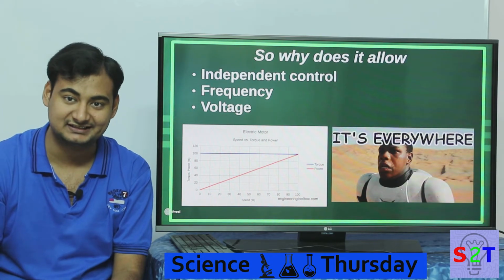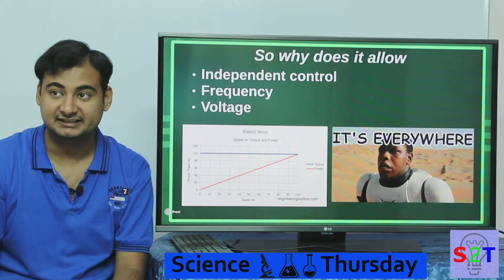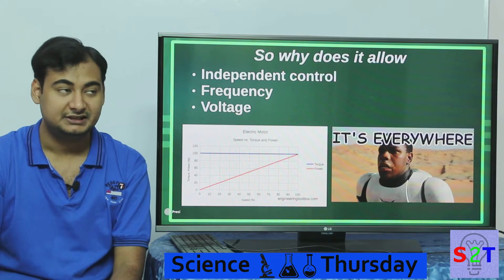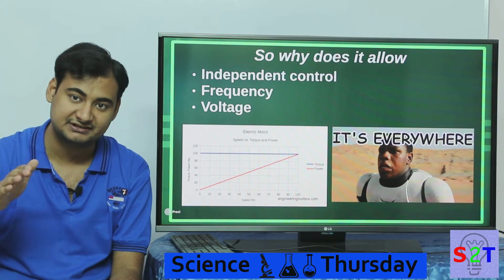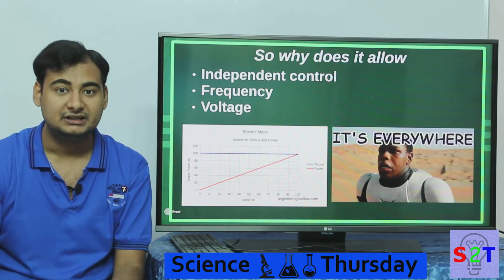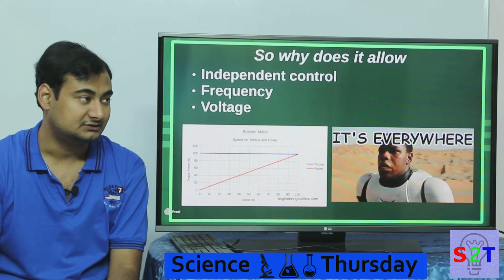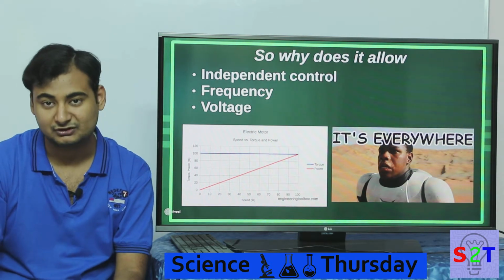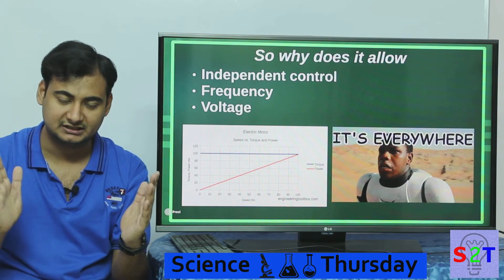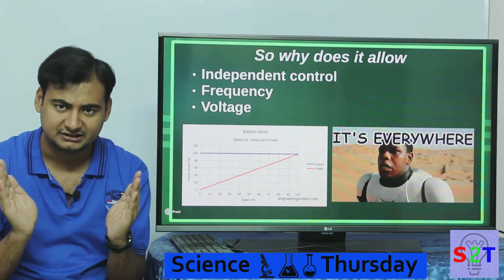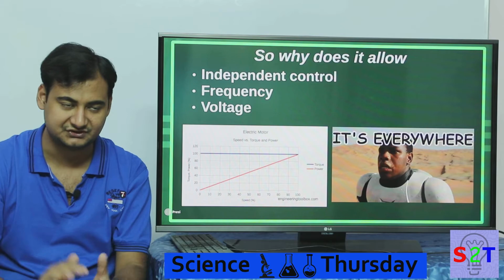This is why your AC nowadays has an inverter system. Let's say you turned your AC on, it's quite hot. It knows it needs to cool the air down, so it can overdrive the motor. It will increase the frequency from 60 Hz, let's say it's designed for, and make it run at 70, so it's getting more work done and it's going to calm it down. Now your room is cooled, and the motor needs to run very slowly just to maintain it, so it will decrease the frequency to 30, 40 or even 20 Hertz, so it's only going 20 RPM, let's just say that.